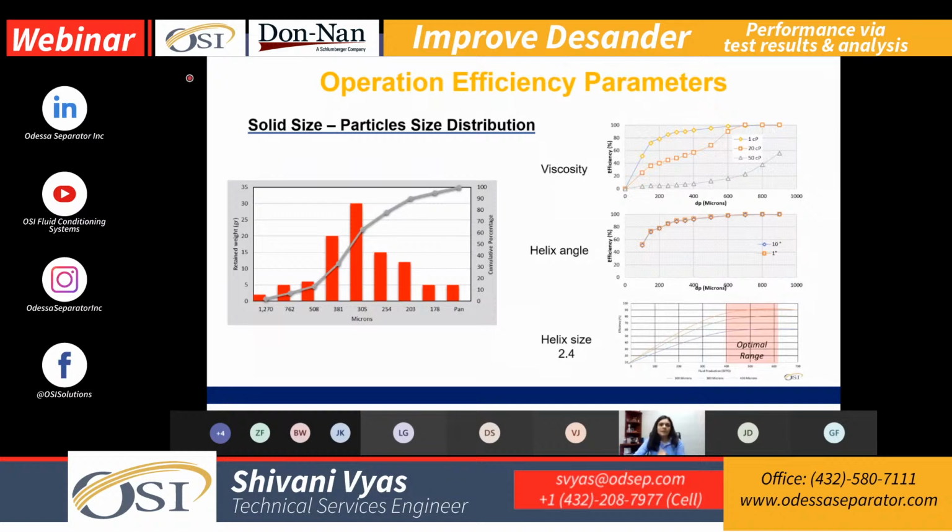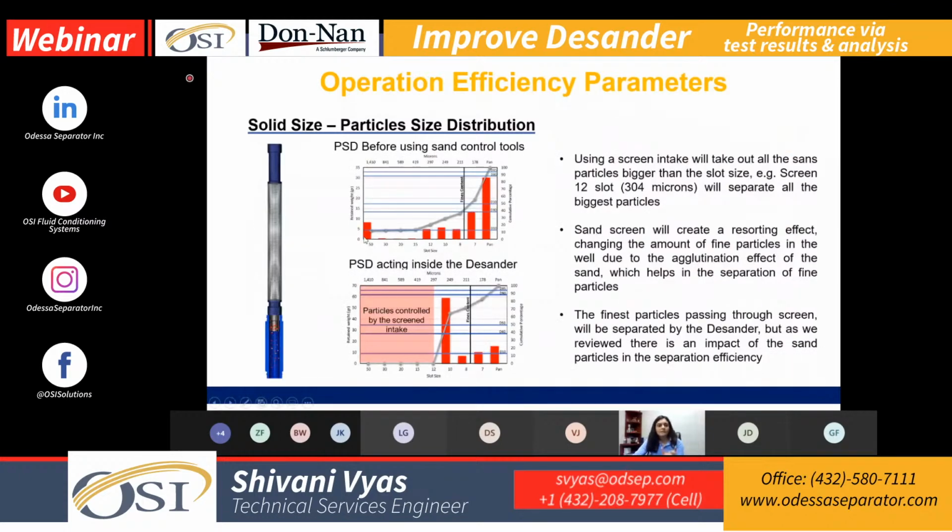And then this is another parameter. So this is what we have, the particle size distribution. We've had the sand sieve analysis, then we can see the sand size in every slot that we're getting. So we can see the percentage of the 12 slot, 10 slot, 8 slot, 7 slot, and then pan is anything that's finer than the 7 slot size in the sand sieve analysis. This is the one that we took before using the sand control. So this is your particle size distribution, and how do we go ahead and size it up?